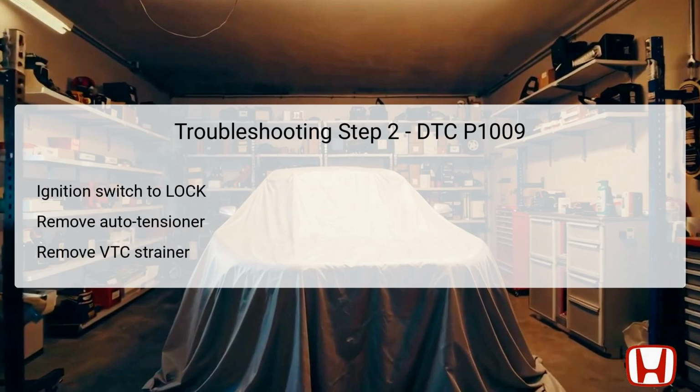Once DTC P1009 is confirmed, turn the ignition switch to lock, ensuring the electronic systems are powered down. The next step involves removing the auto tensioner, which is part of the engine's timing chain system, to access the VTC strainer more easily. After the auto tensioner is removed, proceed to take out the VTC strainer located in the oil passage.